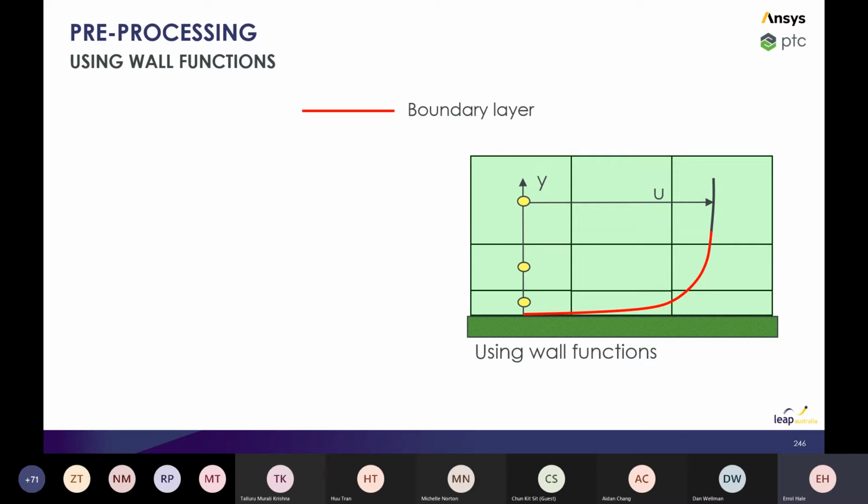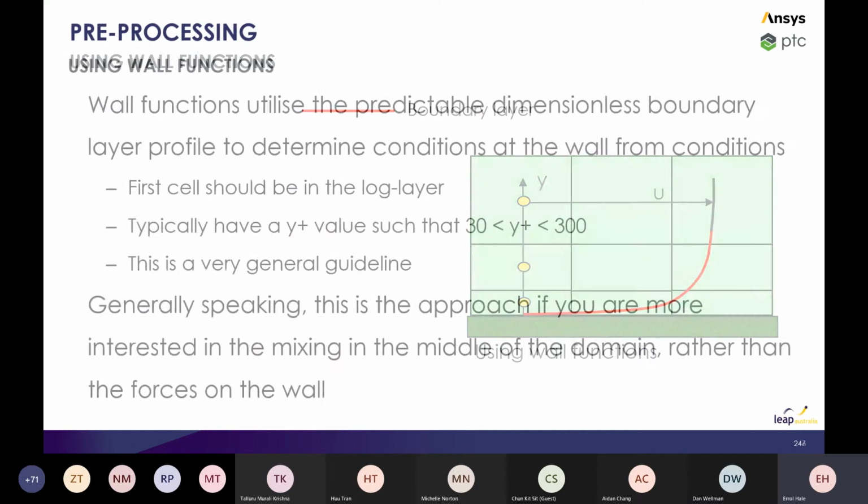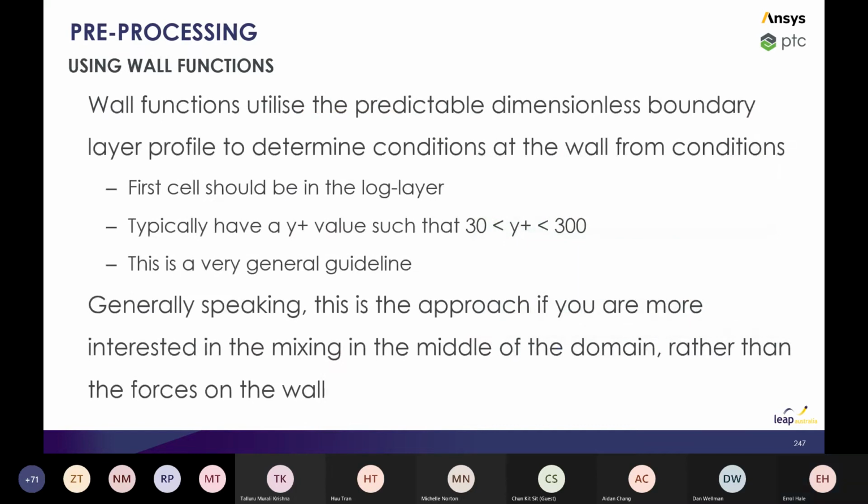We need to know what Y+ value that is, because when we're using the near wall model, using the wall function, typically we need to have a Y+ value of 30. So we can have our first layer height as a Y+ of 30, and our K omega SST model has an assumption about what's happening in the viscous sublayer. It's a well-validated model. It requires fewer mesh elements and can be really useful for reducing the mesh density in your simulation.